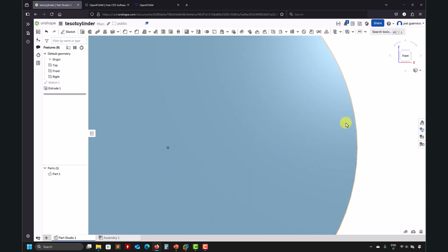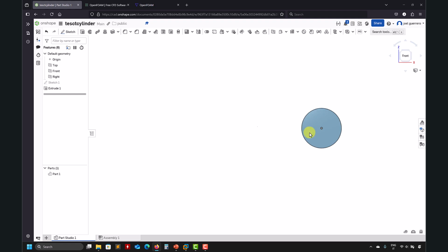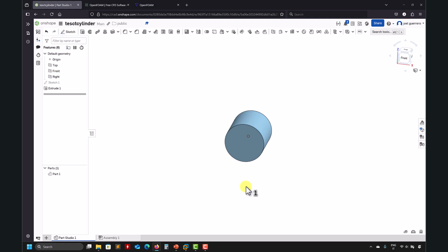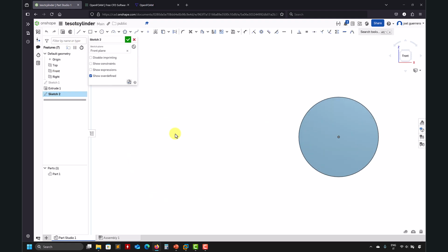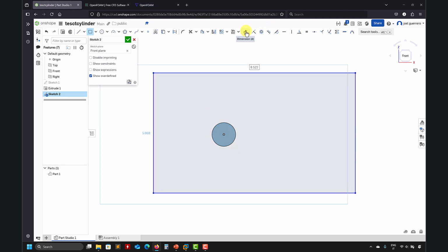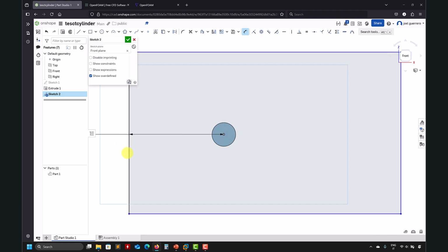And then the next step, as I say, I usually like to create the box, how my simulation is going to look like. So I will sketch in this plane, or you can create additional planes. See here that you have the plane tool. So click there, and you can create it. So it's up to you. So from plane, let me sketch here, normal to screen, and my domain will look like this. You can add dimensions. I'm not going to be very picky with dimensions. So let me put it here 4.